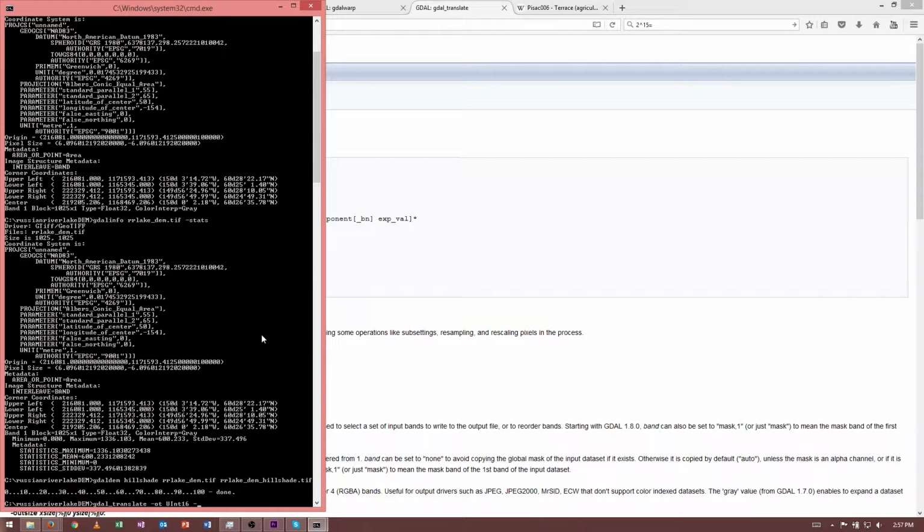For this example, the source min is 0, and for the source max, I'll specify 1,400 meters. This is a nice round number that we can use later inside of Unity, and it gives us some room if we want to sculpt the terrain or deform it to represent snowpack or something along those lines. Then for the destination, min and max will have 0, and then 65535. That is 2 to the 16 minus 1, basically.